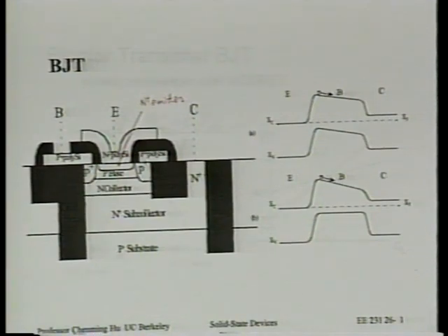So right now we're at a very interesting point, probably near a cross point, that is, people can already design very good CMOS wireless product. Some companies dedicated to that technology only use CMOS to design wireless product. Others still think BJT makes the design easier and work better, right? And some even still use some gallium arsenide chips. So there are several different technologies used.